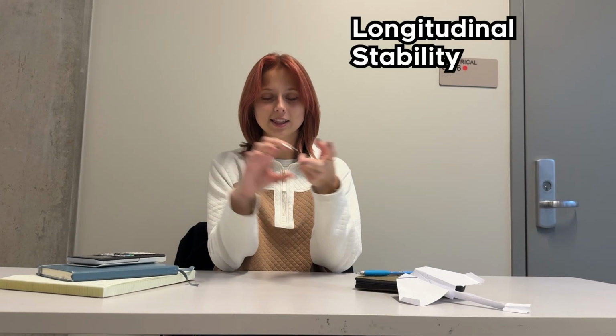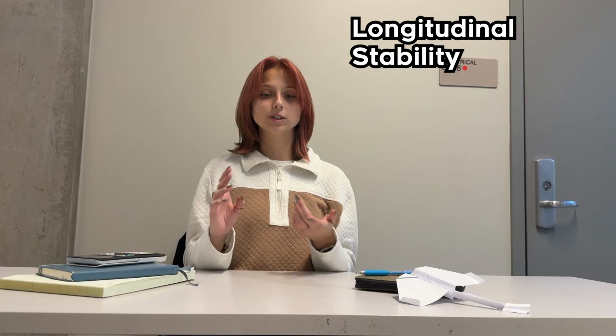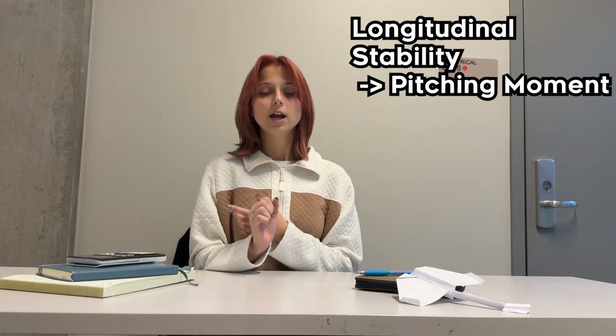So for the stability derivatives, we care about longitudinal stability and lateral directional stability. Now, these derivatives should cause restorative forces for small changes in airflow angles, alpha and beta. To have longitudinal stability, you care about a restorative force in your pitching moment, or restorative moment. So in that case, you want your CM alpha coefficient to be negative. That causes a restoring force by general convention.